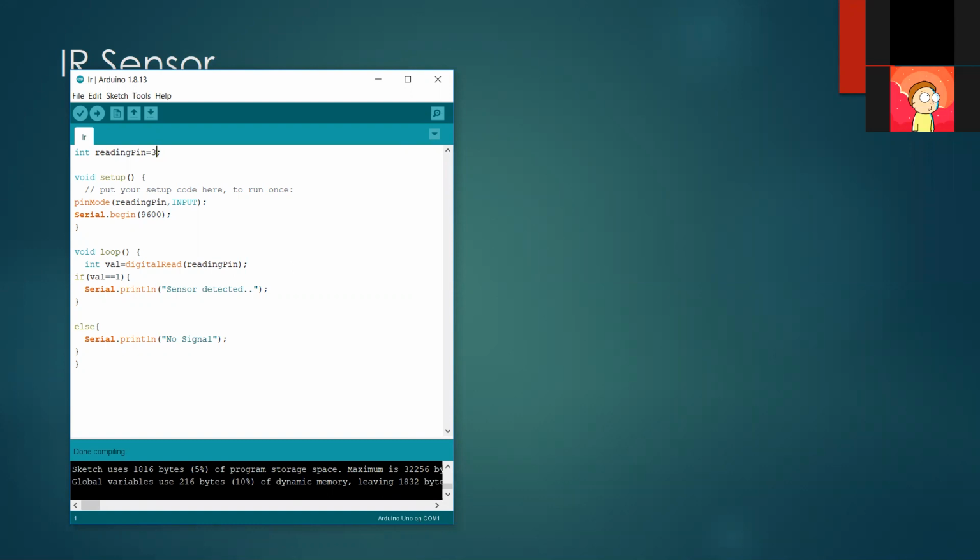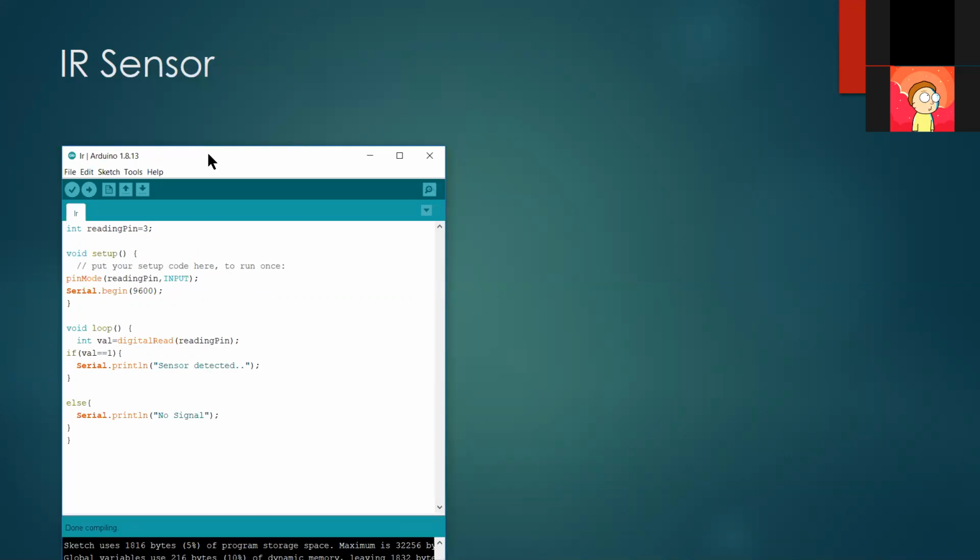So here the IR sensor is like a transistor. Consider that the IR sensor is detecting a white and black surface. Then that IR sensor will give logic levels, depending on the sensor, 0 or 1. Consider white gives 0 and black gives 1. Likewise, you can take the logic levels by using an IR sensor.